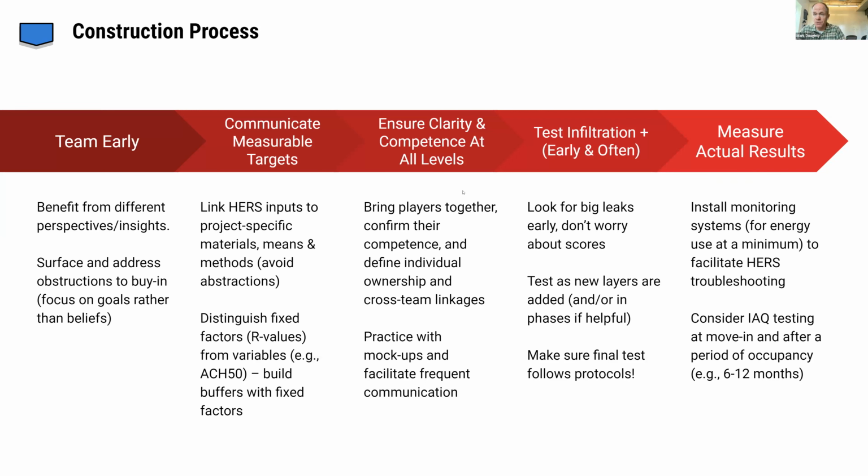The testing side of this, we test early and often. So early on, we do blower door tests. We're really just looking for big leaks. We don't even look at the actual rating. We're just trying to identify where air is moving.